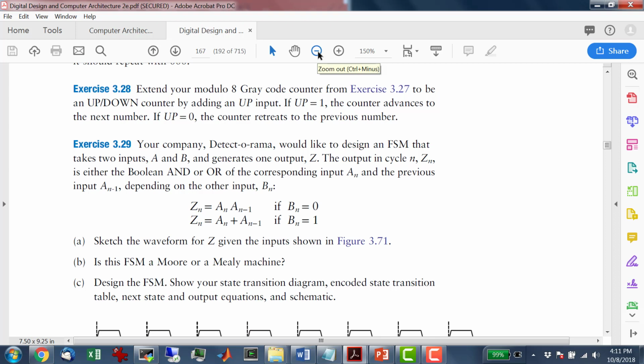And then over here, I have two options as well. So if my B is 0 versus my B is 1, my B is 0, this would be an AND. So my Z would be 1 and 0, which is 0. And over here, the B is 1, so we're doing OR, and this would be 1 or 0, so 1. Right?